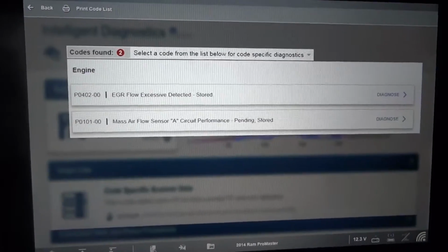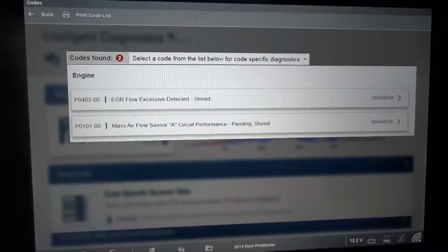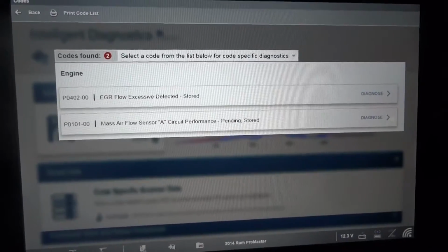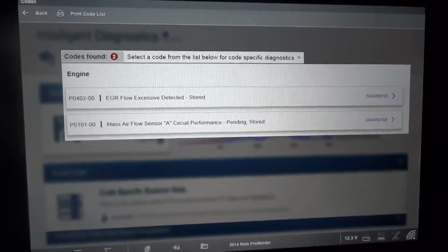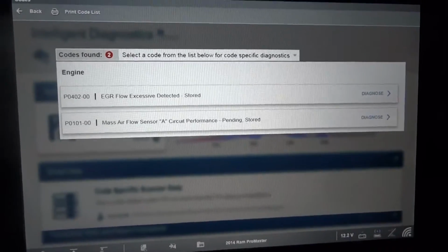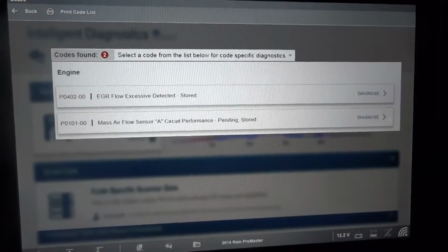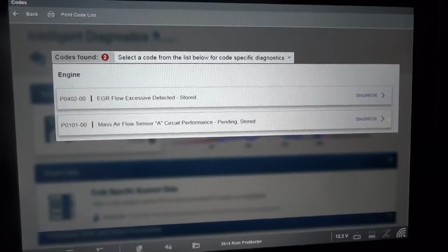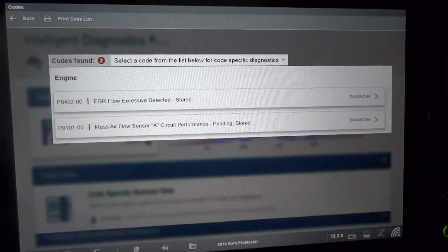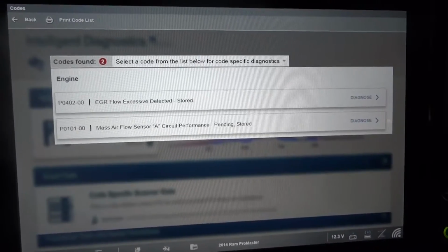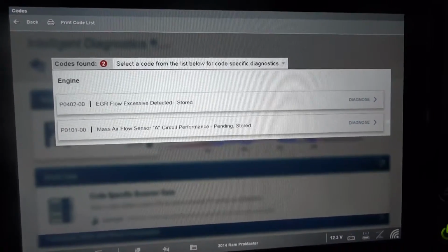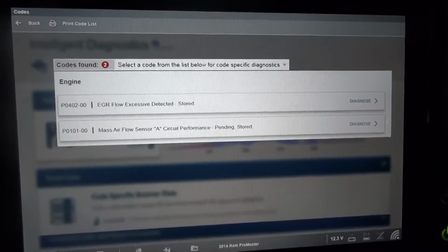So basically what happens when the EGR opens, we allow recycled gases to enter the engine. When these recycled exhaust gases enter the engine, the amount of fresh air that's entering the engine goes down because we are diluting the mixture inside the cylinders. So instead of filling the cylinder with fresh air, we're now only going to fill the cylinder halfway with fresh air, and then the other half is going to be exhaust gases coming through the EGR.